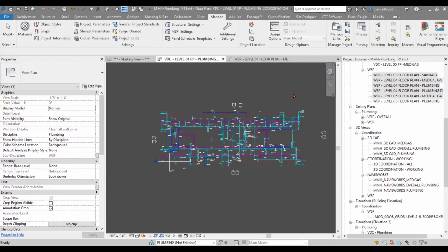So at that point, once we clear through all this type of information, and after we've, of course, had our initial coordination meeting where we should have received our BIM execution plan, we know exactly what we need to cater towards. So line types, colors of systems, what needs to be shot off into Navis and how it needs to be shot off into Navis, so those NWC files get created. We'll start to drop in our project standards.